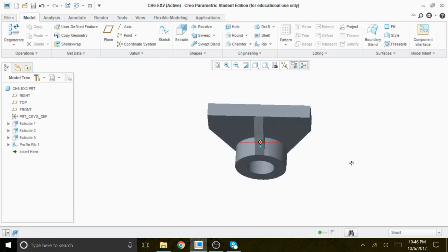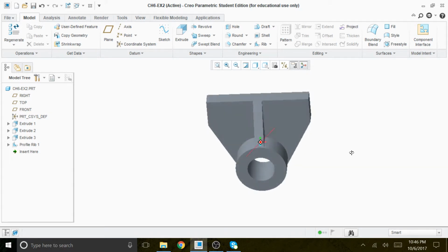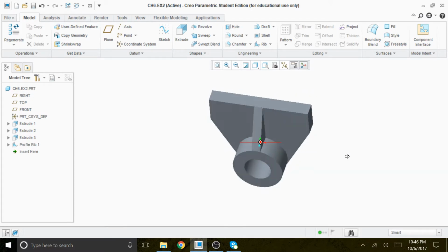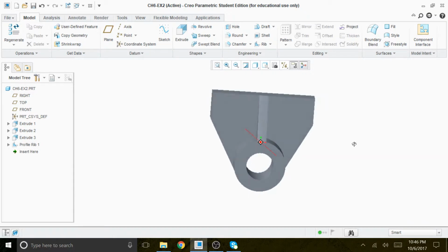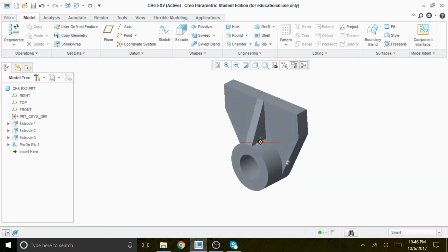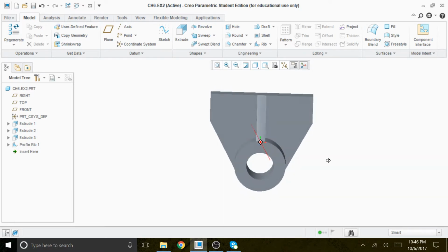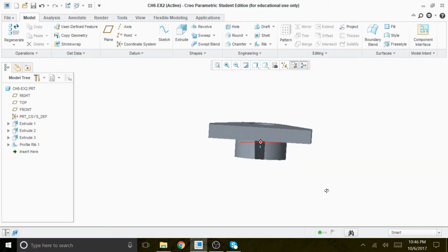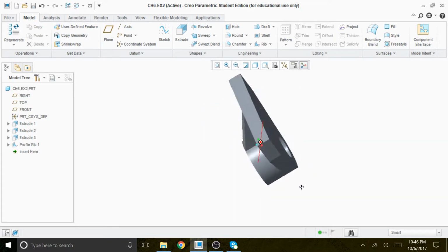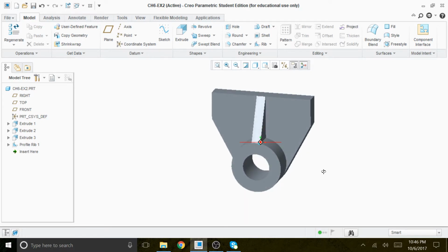Again, someone asked me in class, how do you know which view we're looking at? The standard view, according to the US system of drafting or mechanical drawing, we just look at the face. This is the isometric. If you look at this face, we call it the frontal plane or front view. If you tilt it like this, that will be the top view. And if you look at the side, that's the side view. Those are the 3 principal views.